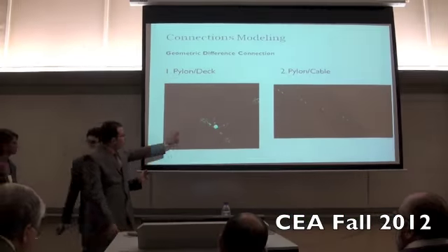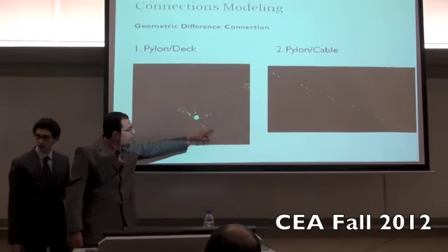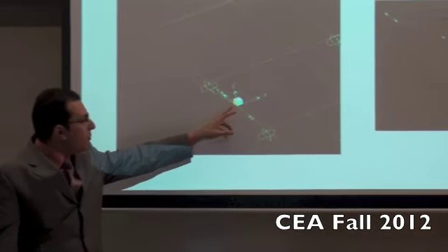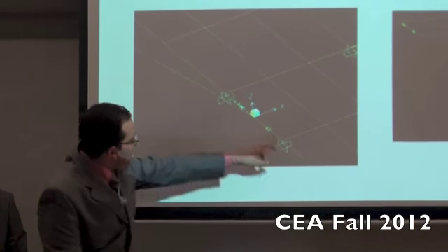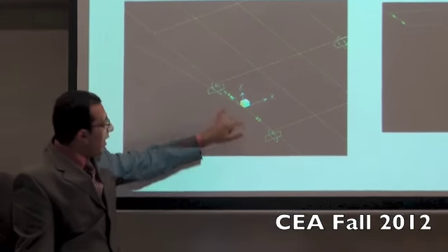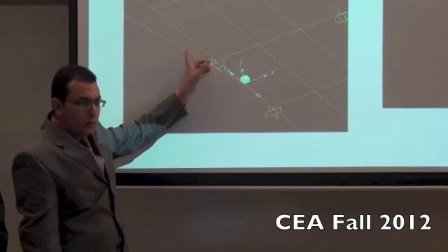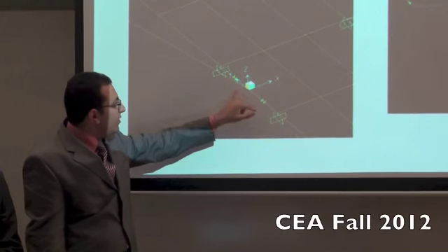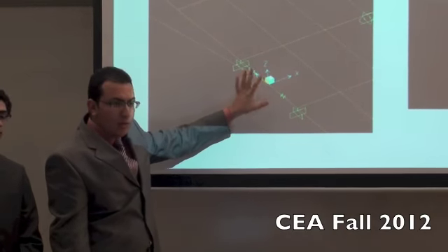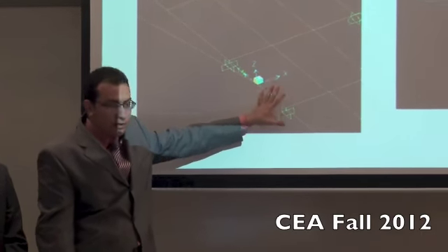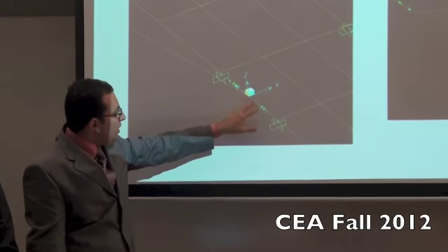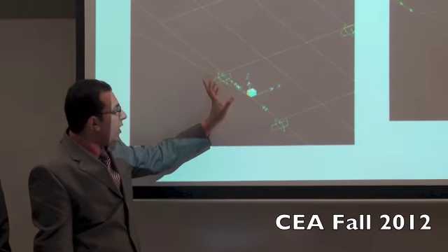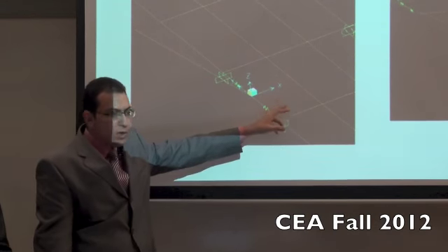We have two webs and one pylon, and the pylon is big enough to cover up to these two places. So we are also representing the pylon with a frame, and that frame is connected with two link members so that they transfer the moment, because we have a moment connection between the two webs or the deck link and the pylon. So we use these two links so the moment is transferred between the two webs.